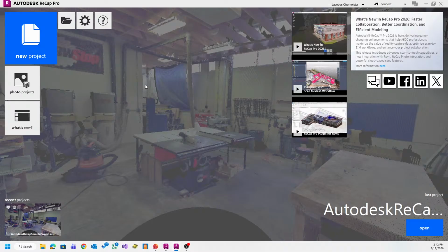If you ever use this kind of data in Revit, like I mentioned previously with the tracing, you can use that point cloud data, you can snap to it, which is really, really cool, but you still have to draw your walls, you still have to draw your slabs, etc. You just use that point cloud data as something to snap to, as something to reference your model. So just please be cognizant of that.